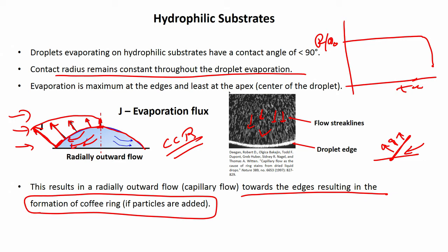That means, if this droplet has particulate matter, then all the particulate matter will be transferred from the droplet bulk to the droplet edge, just because the contact line is pinned, in order to make up for the depleted solvent. And so, you naturally create a convective environment inside the droplet, even though the droplet is vaporizing in a diffusion based way.